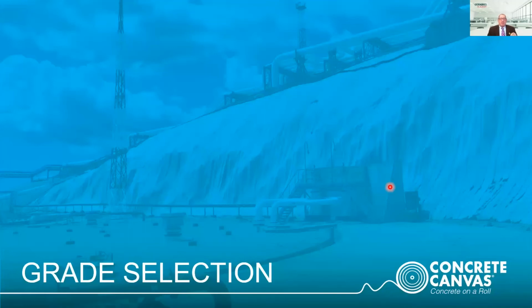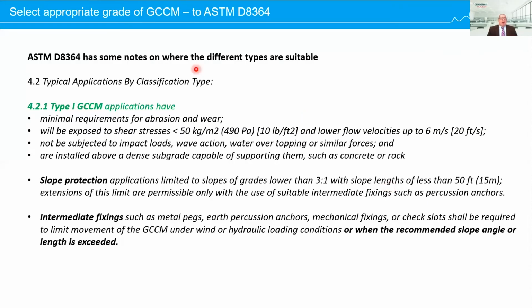First step is grade selection. ASTM D8364 has a lot of written description of where type 1 GCCM applications should be used. Basically, it's for applications where there are minimal requirements for abrasion and wear, where exposure to shear stress will be less than 490 pascals, and for flow velocities up to 6 meters per second. The project will not be subject to impact loads, wave action, water overtopping, or similar forces.